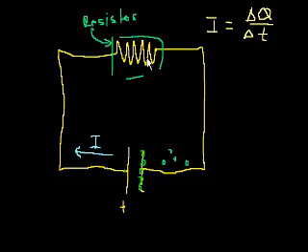But when they get to this resistor, they start bumping into things, and this limits how fast the electrons can travel. So you can imagine that if this object right here is somehow the rate-determining factor in how fast the electrons travel, no matter how fast the electrons can travel after that, this was the bottleneck. So even though electrons can travel really fast here, they have to slow down here, and then they can travel really fast here. The electrons here can't travel any faster than the electrons through this.